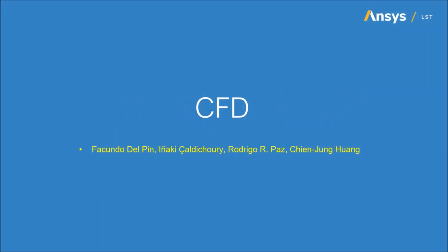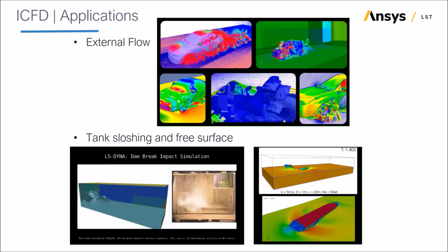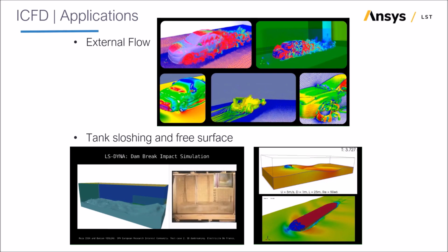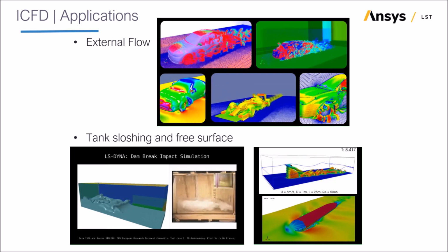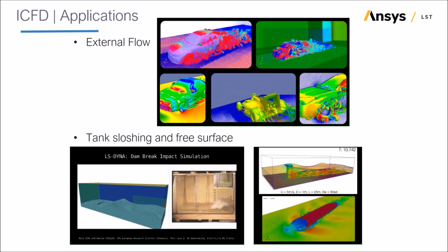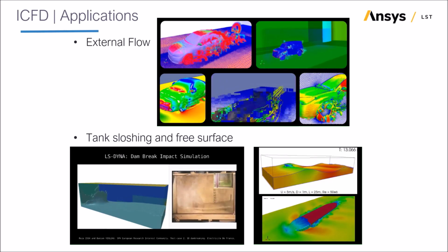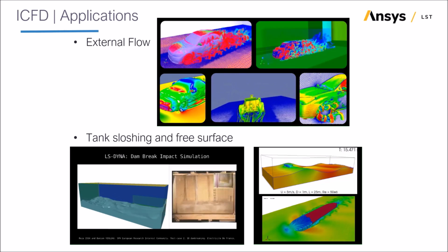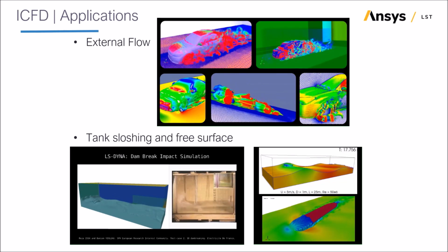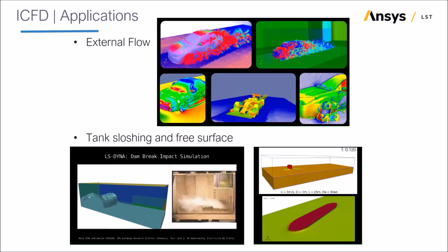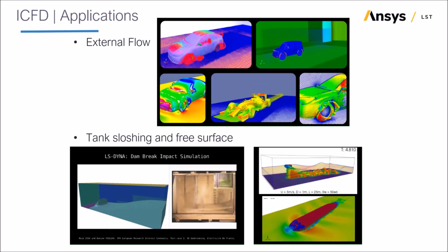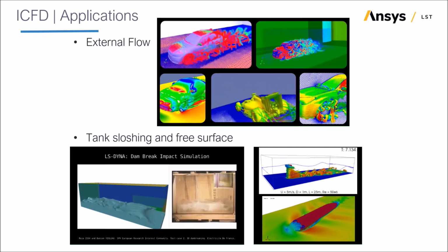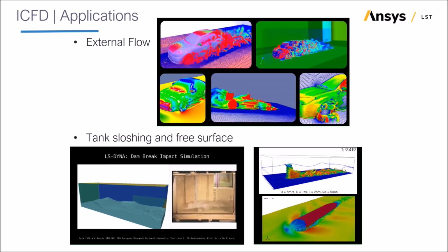Now I'll say a few words about LS-DYNA's CFD capability. Now you might ask why CFD capability was added to LS-DYNA in the first place, when there's already several good CFD codes out there. One reason is that it's part of the drive towards multi-physics. So for instance, there are many fluid structure applications where normal CFD codes couldn't model the deformation of the structure. But the objective is also for LS-DYNA to be cheaper and faster for purely CFD applications as well.